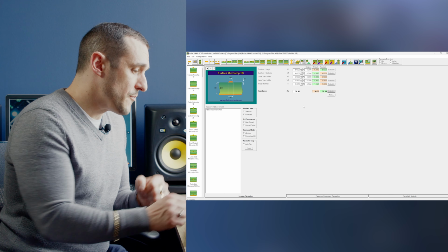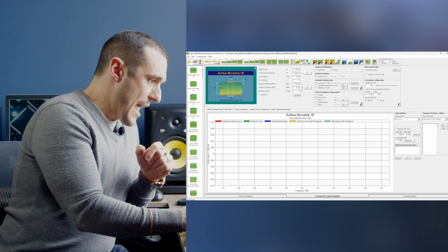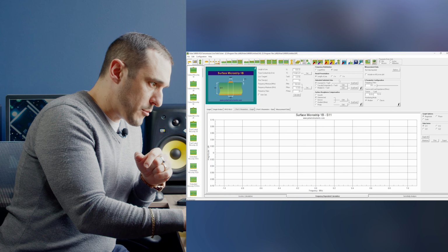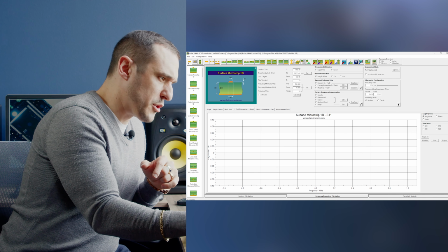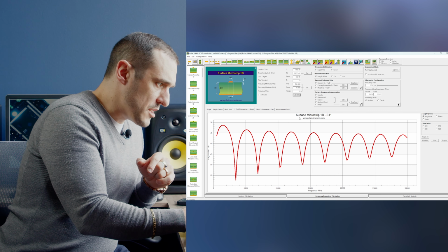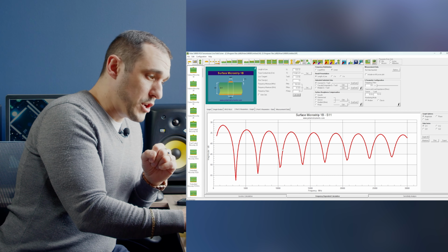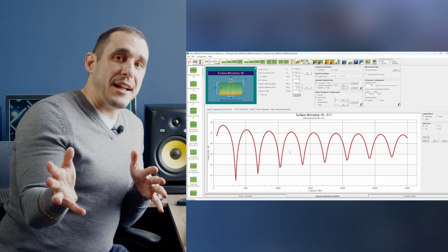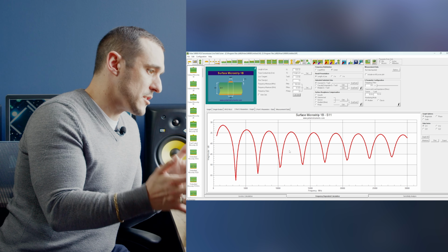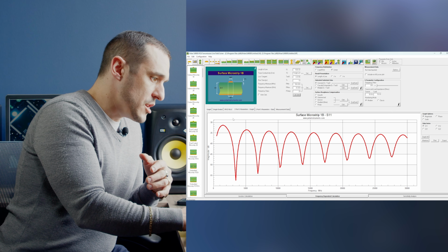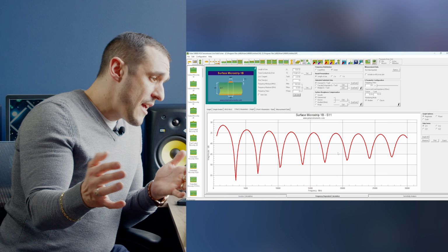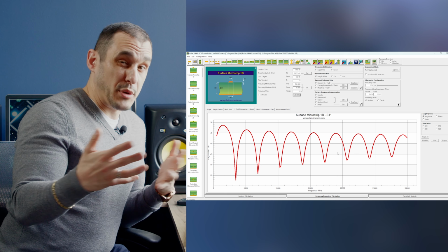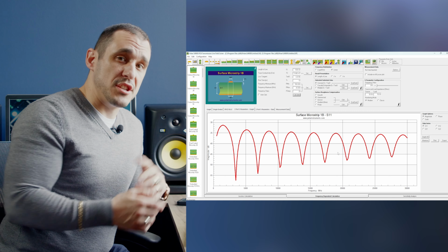So that's pretty good. So now let's take a look at what happens with the S parameters. Here, if we go ahead and calculate this up to, let's go up to 30 gigahertz. You can see here what the S parameters look like. Pretty good. So this is a pretty good match to a 50 ohm reference impedance, or 50 ohm target impedance. You can see here that we have very low return loss, below negative 30 dB. That would be pretty acceptable for pretty much any high frequency line that you wanted to use in the design.